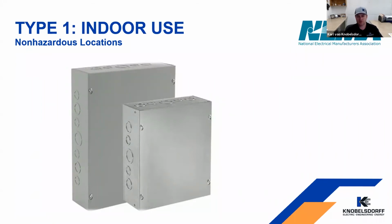One thing that you have to watch out for, if you'll see, these boxes have concentric knockouts on the sides of them. So when we're dealing with hazardous locations, we have to do assured bonding all the way back to our service. So what that means is if I have a motor in a hazardous location, I have to have assured bonding, not just using my conduit, all the way back to the service, so all the way back to your MCC room. So you can't just use a conduit, pop out one of these fittings and stick it in that hole. It also has to have a bonding jumper on there and bond all the way back to the service. So that's another thing that we find a lot when doing audits at facilities or doing PMs, where the bonding doesn't meet code and was missed during installation.